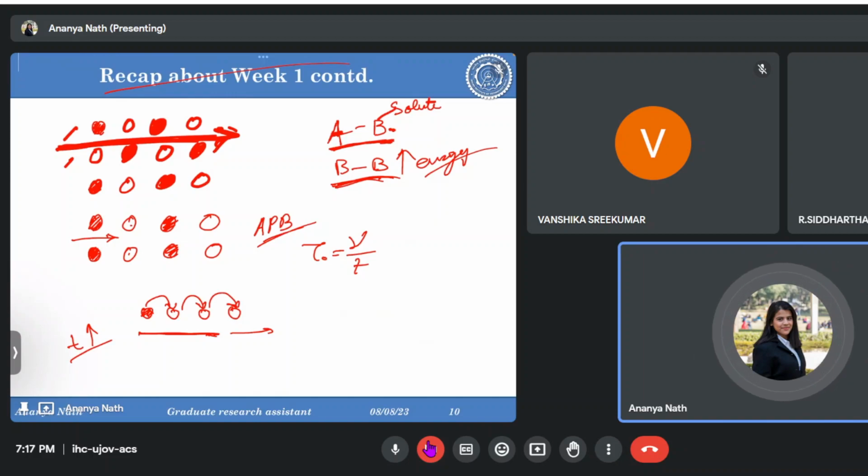But there will be a time when solute will accumulate before this, making some other type of microstructure, which will be a difficult barrier for the dislocation to break. So if you see, there is a magnesium or Mg2Si precipitate. There also the precipitate restricts the dislocation movement in the 6000 series of wrought aluminum alloy.